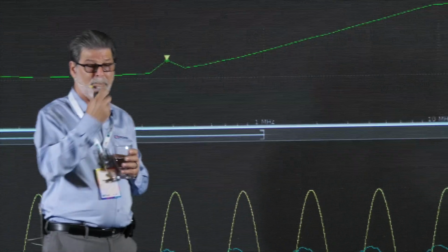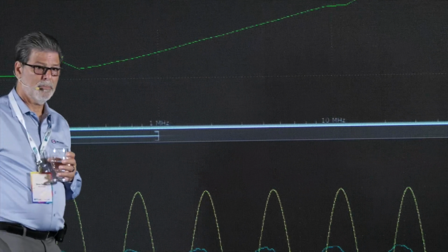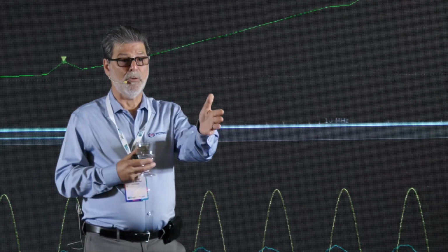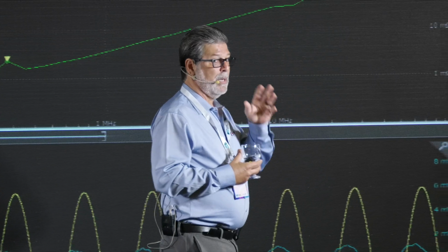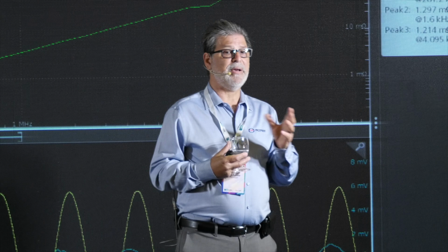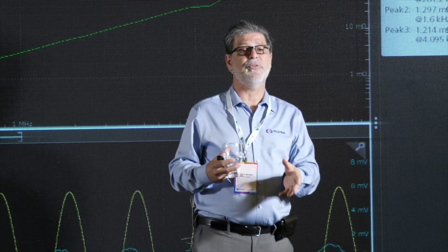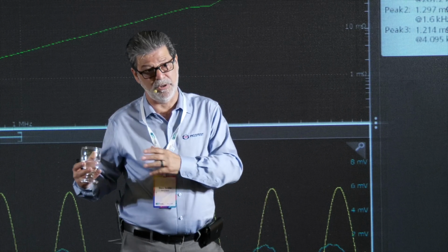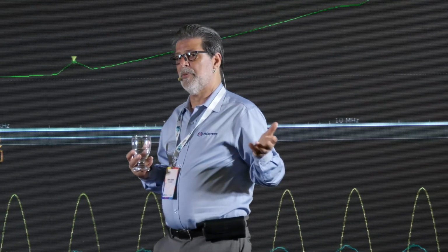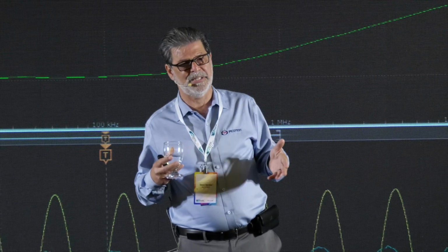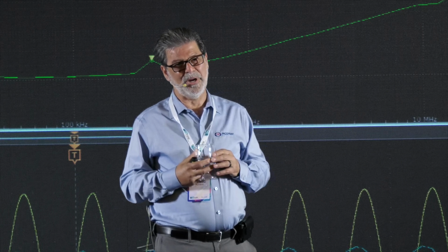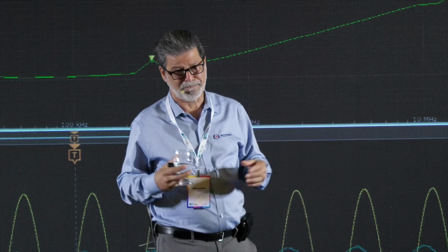Yeah. How do we know to choose the right sample rate of the VRM? The right switching frequency? So there's not really a finite answer, but I will give you some guidelines. One is that if you have a choice, you want to push the switching frequency to a band where you're not sensitive to noise, where you have your lower sensitivities. A lot of lower performance clocks have phase lock loops that are very sensitive in the band of maybe around 100 kilohertz. 100 kilohertz switching frequency would be a really bad choice for that.